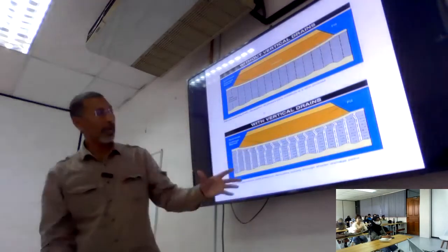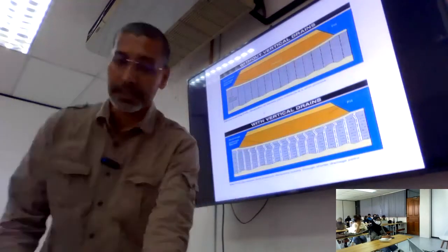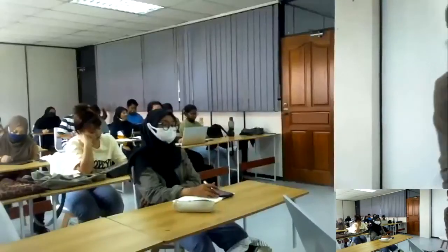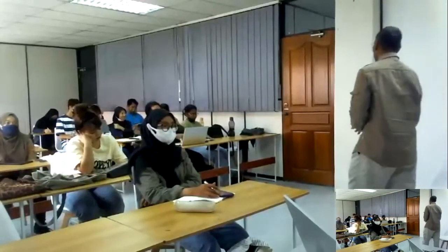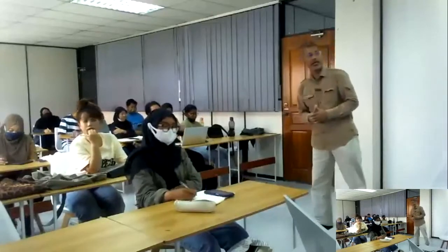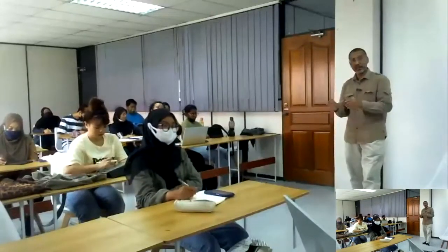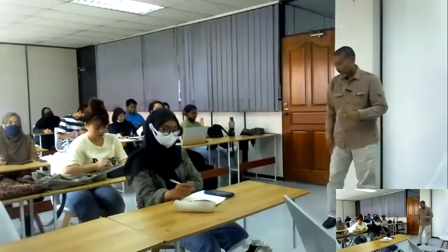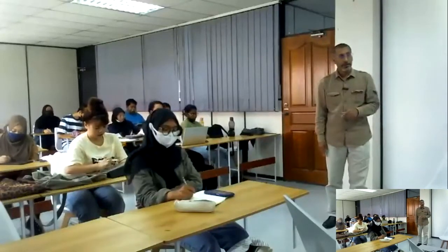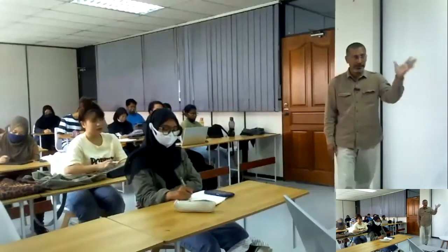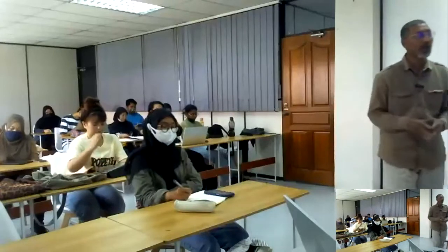So that's how a vertical drain works to expedite the process. This is for your information: typically spaced 3 meter center to center. In Malaysia, we have some of this, but now we have more vertical drain.